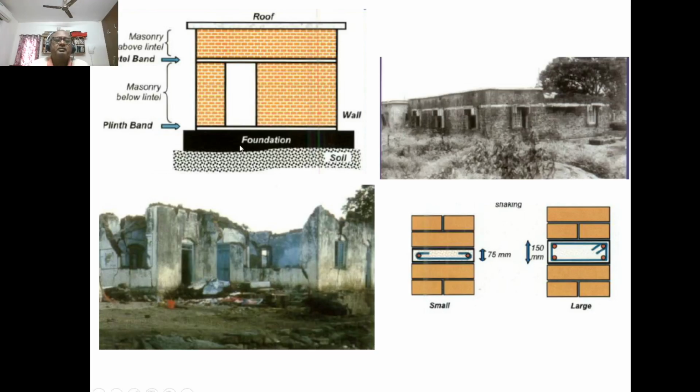In the masonry structural system, normally if you have issues like failure, as we can see here in this picture, one of the solutions is that you should have a plinth band, a lintel band, and a roof band. This is what is normally recommended in the code book also. If you have that, you can have the best system, so that the lateral resistance becomes slightly improved. Normally, this lintel beam is 150 by 230 or whatever. So we will have four rods and one stirrup.